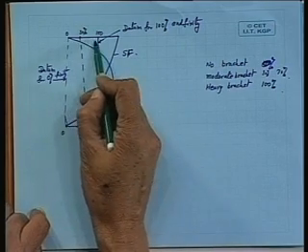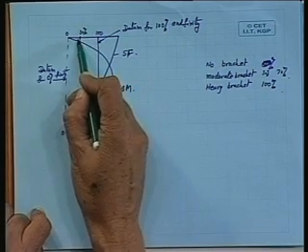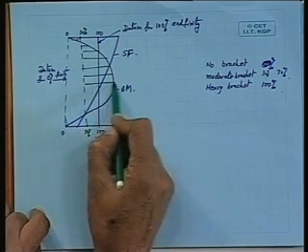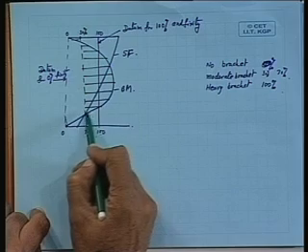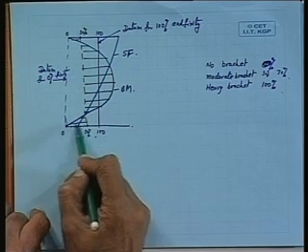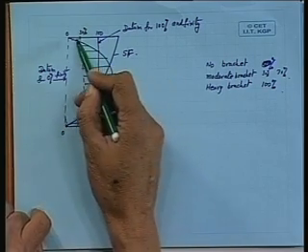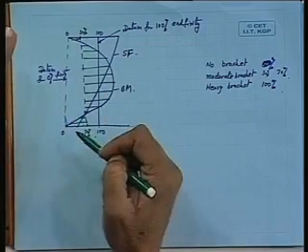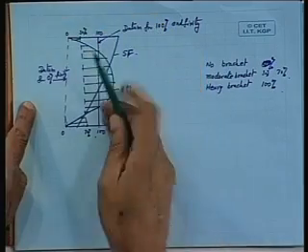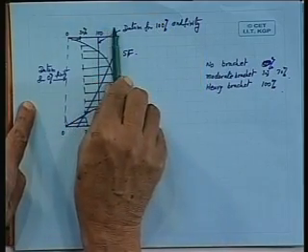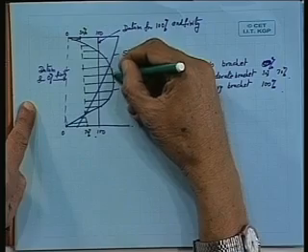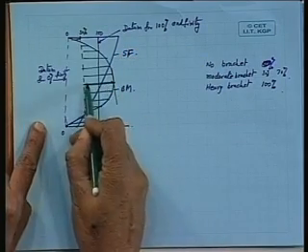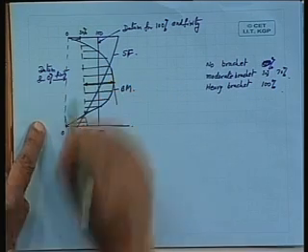And now, if I measure the bending moments like this, this becomes the bending moment curve for this particular condition. Based on that, now you have to draw a parallel line with respect to this and find out where the maximum is coming. This is the value of the maximum bending moment, and this is the location where it is acting.